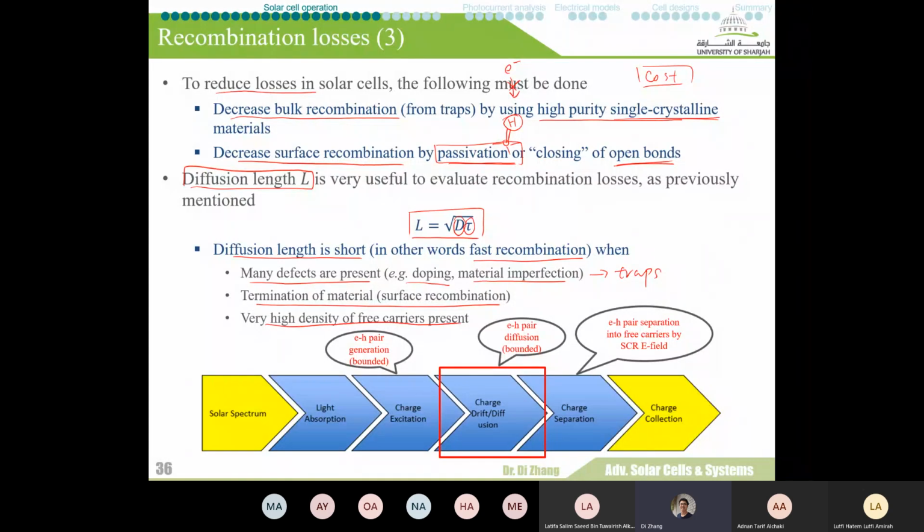For that, I would like to bring your attention to the recombination rate equation we mentioned earlier. If you remember, the recombination rate equals the delta of the carrier divided by the lifetime of this carrier. Even though sometimes we may have the same lifetime, the same tau, the delta here comes from the actual concentration of carriers minus n0, which is the intrinsic carrier concentration level.